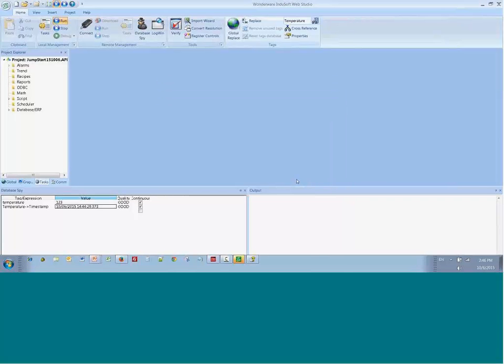In addition to that, I can use this same syntax here and say temperature minus greater than high limit. That's the name of that property, and it'll show me that that value is 90. I could change this, and let's say that I notice it's rewritable. I could say, okay, I want to make this 95 and change that limit during runtime.